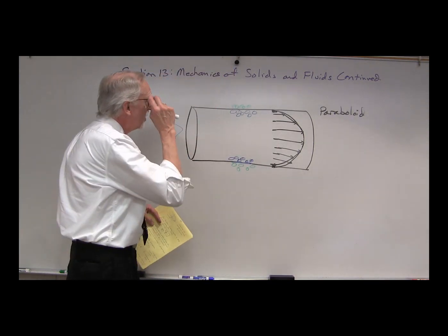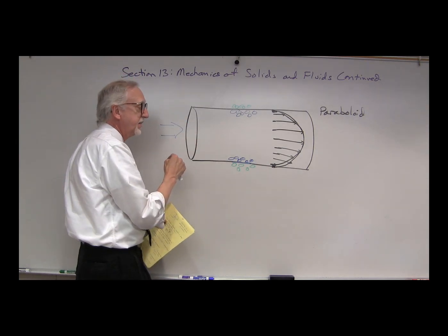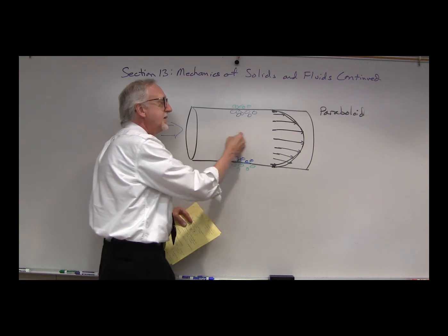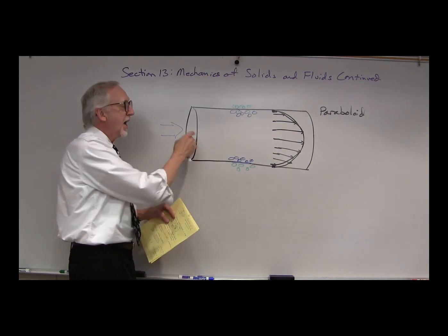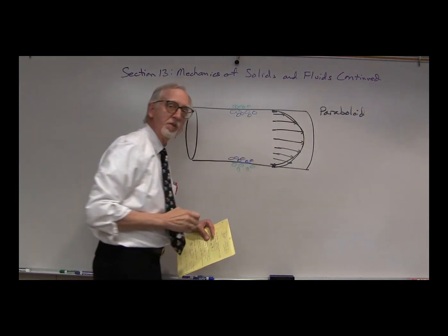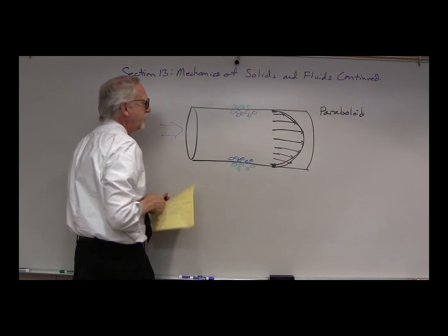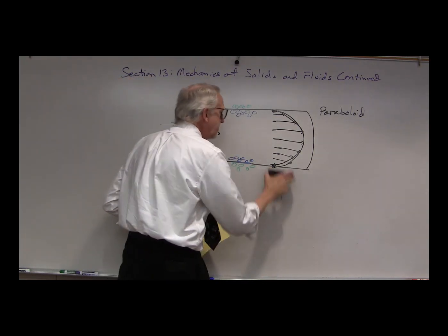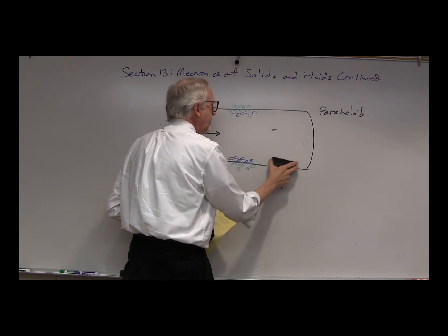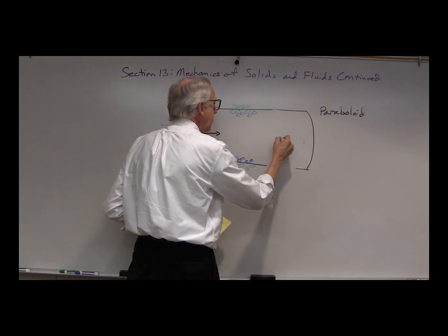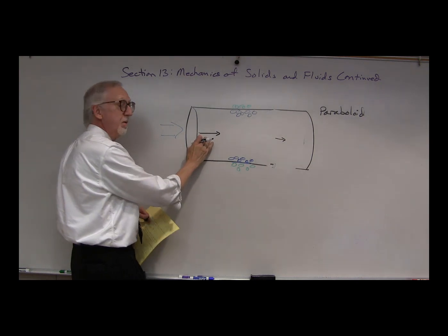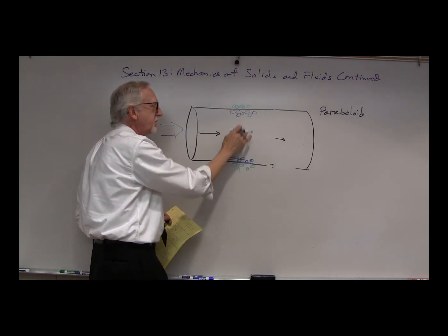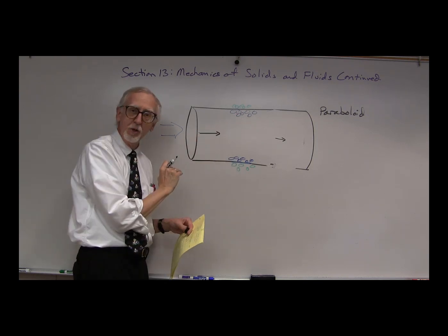And then, because of the viscosity, internal forces of the fluid are going to decrease the pressure as we move along the fluid flow. Because of these forces, the pressure over here is going to be higher than the pressure over here, because the forces over here have to overcome these viscous forces of the fluid itself.